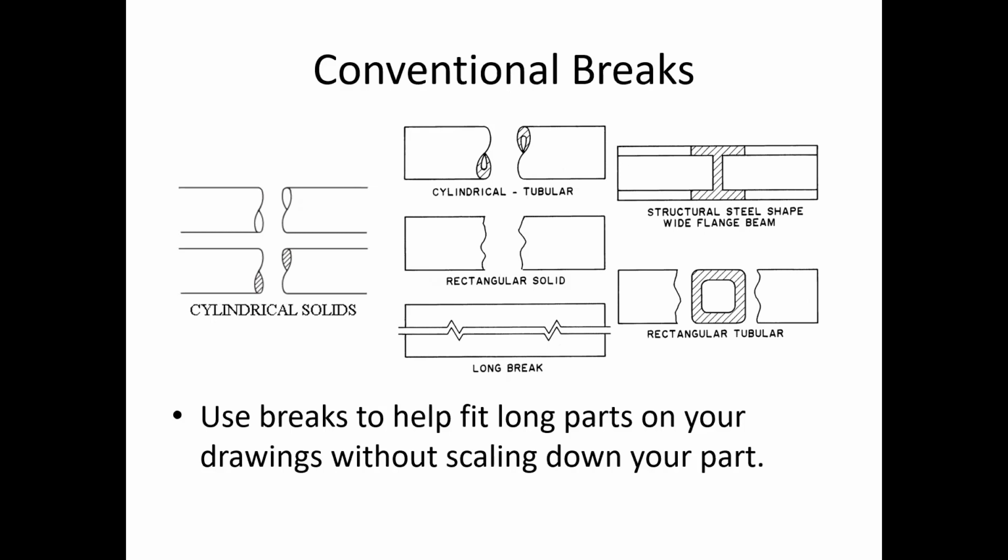And as you start to dimension, if you've got a drawing on an A size sheet that's 1:4 that would really fit 1:1 on a B size sheet, when you start placing your dimensions, they're really crowded and it's very hard to make it look easy to read. And that's kind of your clue. It's like, crap, I shouldn't do that at this scale. Let me rethink this.